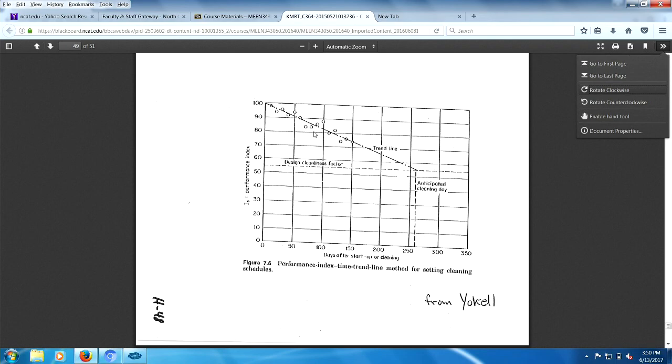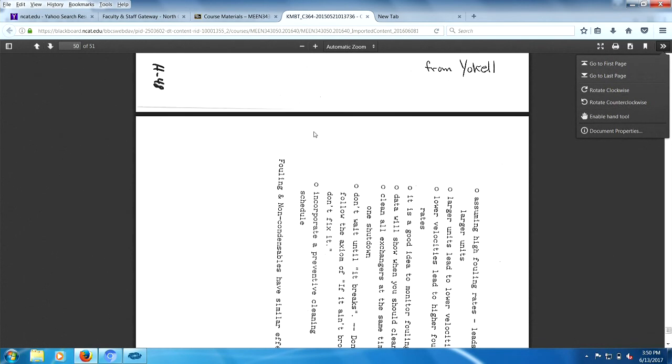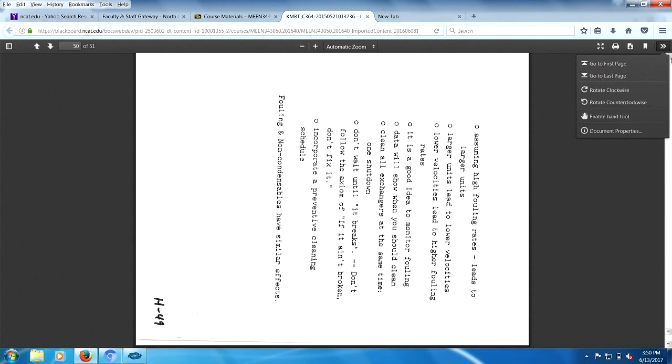So a 1-2 heat exchanger: one pass tube side, one pass shell side, two passes tube side. We've already gone through that. You don't want the 4 and 6 pass type exchangers. Keep it simple, sweetheart. KISS, keep it simple. Standardized, all your cleaning methods are the same. Everybody knows how to clean, and voila, everybody likes you again.